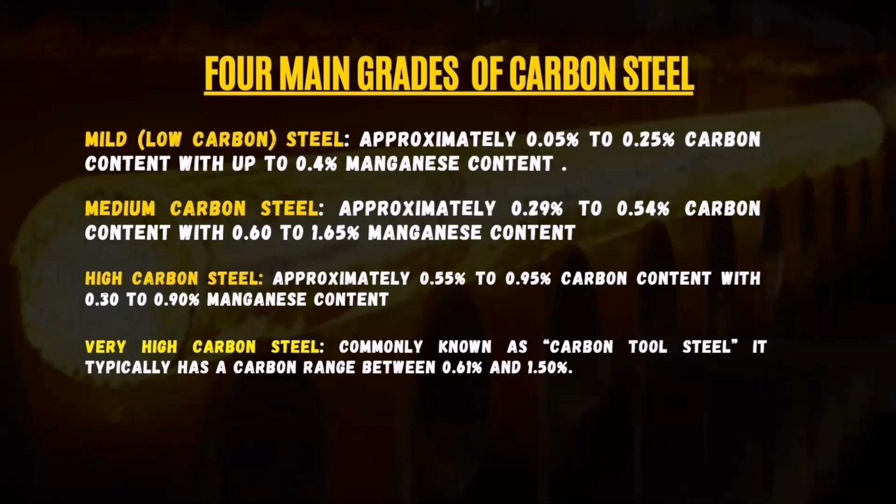To enhance strength and reduce brittleness, carbon steel pieces may include traces of other elements such as manganese. Manganese is present in carbon steel because it reduces the critical cooling rate during hardening, meaning it increases the hardenability of a steel.